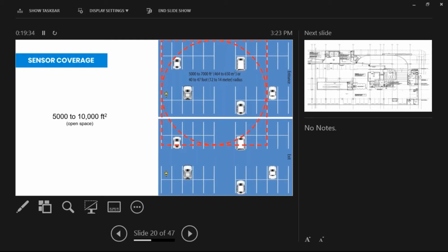So just like spacing out light bulbs such that you have enough light to cover that large meeting room or a large gymnasium, you're going to place sensors out throughout an envelope that you want to monitor, such that you've got a decent amount of coverage and your sensors can react to the concentrations of target gas as the ambient air diffuses and convects and spreads that target gas throughout the ambient atmosphere.